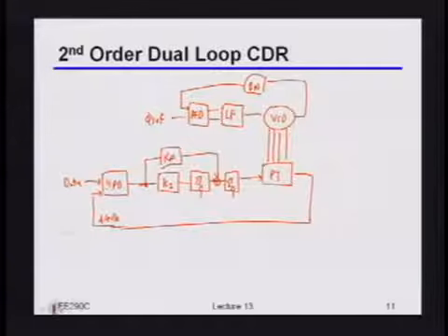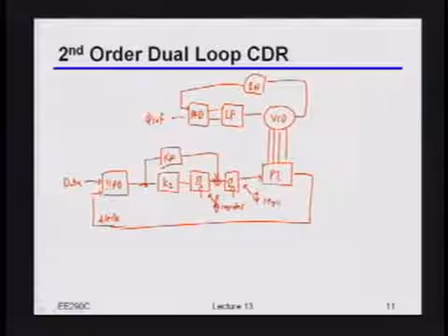So again, just to make sure the intuition is clear, this register here would be the frequency register, and that output over there would be the phase register. So the frequency register tells you what that ppm offset is between the two clocks, and the phase is telling you what the instantaneous phase value is that you should be using to then, of course, control this phase interpolator here. Okay? Does this make sense to people?